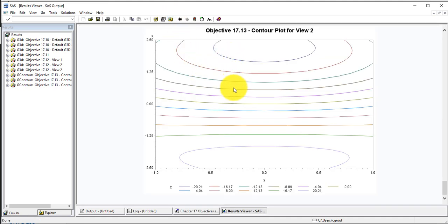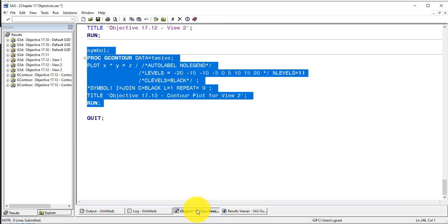So I get different colors for the contours. It prints them here. You can see the values because I've chosen a graph that has some symmetry about 0. It's why we see things symmetric about 0. In practice that doesn't happen. For me, it's difficult to tell one color from the next sometimes. So that's why I favor this auto label option and then turn the legend off. That way it prints the value of the contour on the graph.